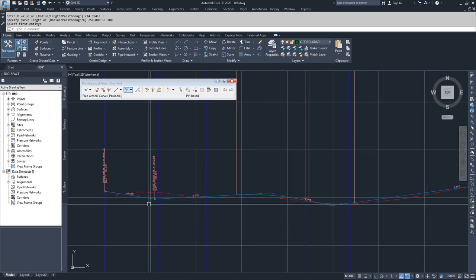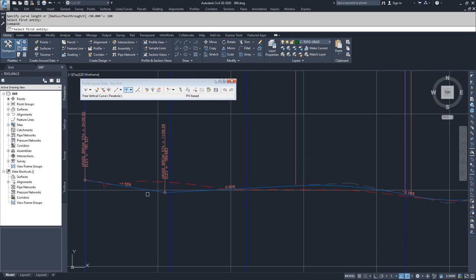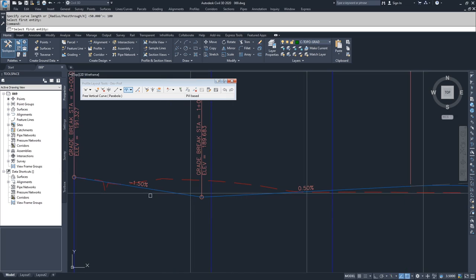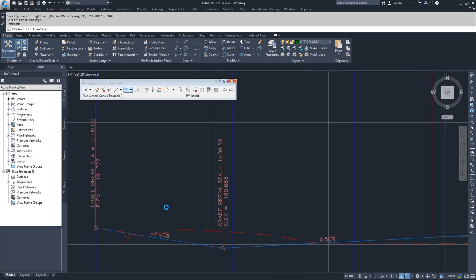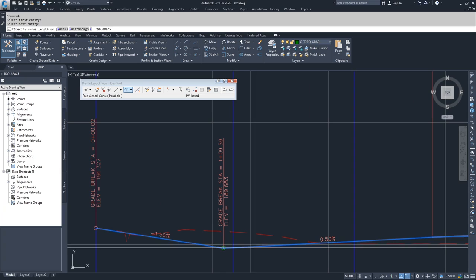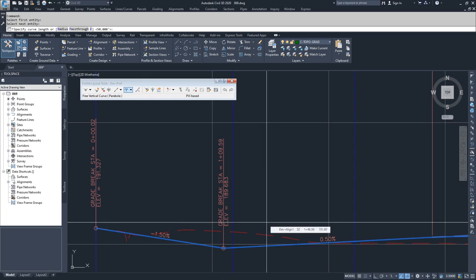I'm going to go ahead and add another one in here. I'm going to, again, do a free vertical curve parabola. I'm going to select this entity coming in and this entity going out. And because this is going out of the road here and into my site, I don't want to expand too far out, and I don't want to disrupt what's going on with this ditch here and the existing road. So I'll probably go with something a little smaller. I might go with 100. I think I'll try 100 to start with, and then we can see if it's too large.